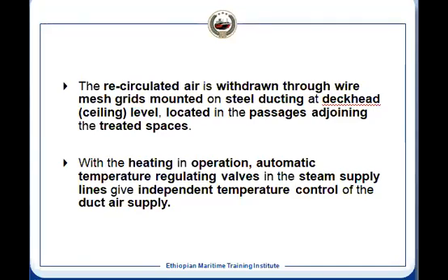Now, heating can be manual, or it can be automatic. So automatic means you have the air handling unit where you have the heating coil, for example, and then it is the steam heating. So there will be an inlet, there will be an outlet, and there will be a control valve because the flow of the steam will be controlled.